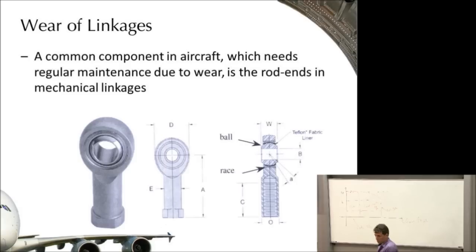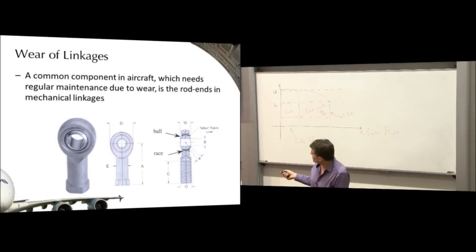So every time you move the stick from one side to the other or up and forward, your control surfaces are moving, and those control surfaces are pushed in and out by push rod linkages, and they all have these cup and ball connections on the end. Now, they're generally not lubricated. These things are just free running in there. They might have bearings in them, or a Teflon, but those things can wear out because they're constantly moving relative to one another.